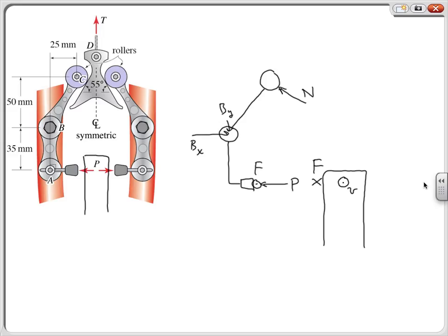That is, the wheel coming forward would be trying to drag the brake pad towards us, out of the plane of this figure. Now this is going to be reacted at our bearing B, and so in addition to the forces Bx and By, we're going to have an axial force on this bolted member, which is going to be into the figure.